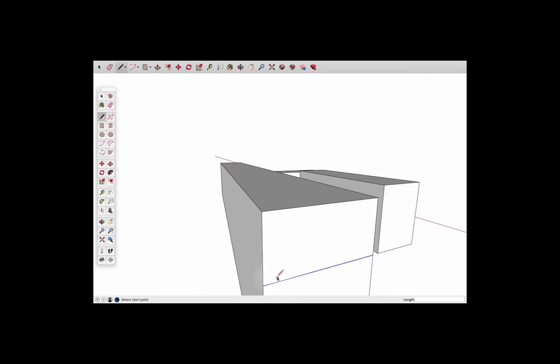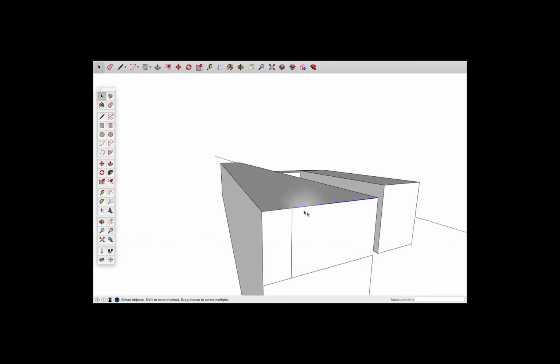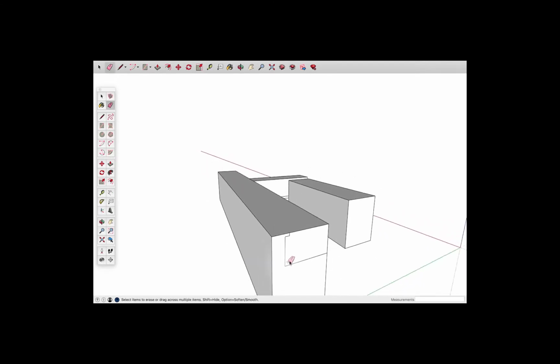And what I think I'll do, I'm going to take this edge line, and I'll copy it over about 5 inches. And that'll be the edge of my counter. And I can even copy the countertop here, although I think I'm just going to wing it and give myself a little profile for the top of the counter. Erase that. So you can see I'm starting to get a sense of what this guy might look like from the end. And now I can just push-pull this all the way down to the edge.